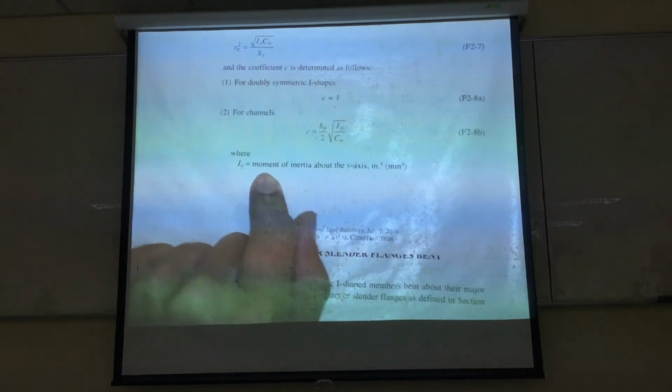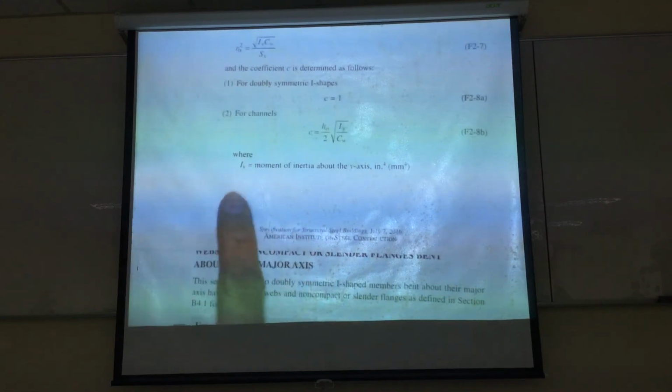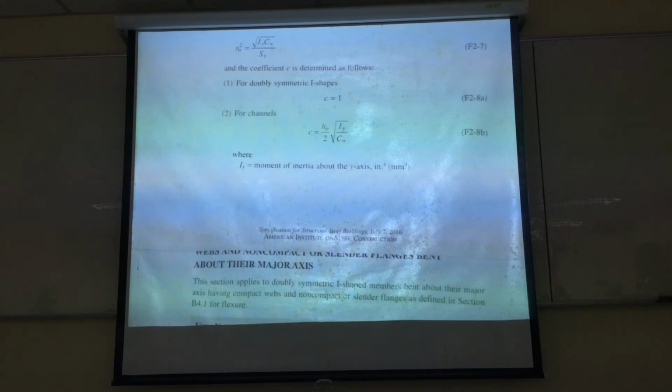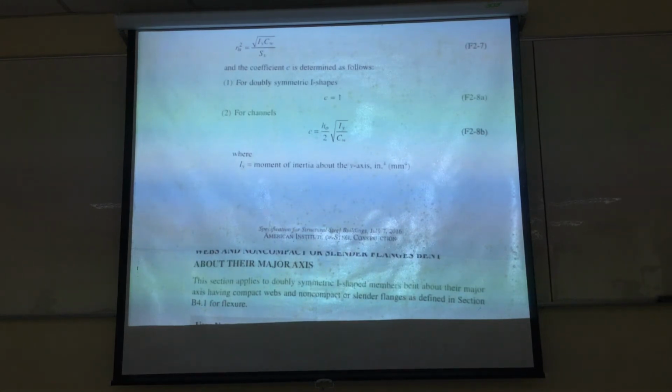Okay, this Iy. Generally, if they don't say that it is the moment of inertia of the flange, individual flange, then this is taken from the steel table. From the steel table, the Iy includes 2 flanges, and the I contributes from the web. Web is like nothing, less than 1%, so okay, you can include the web. It is 0.1% or maybe smaller, okay, very small figure.